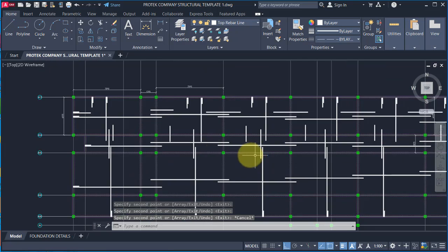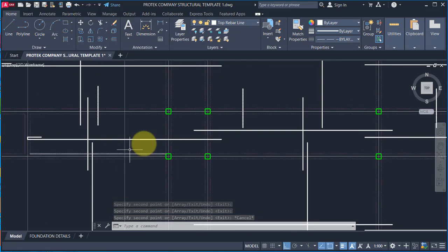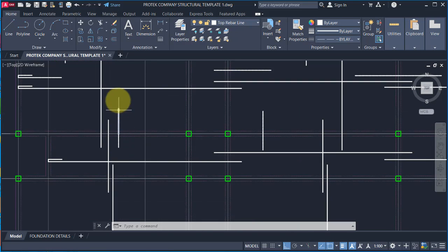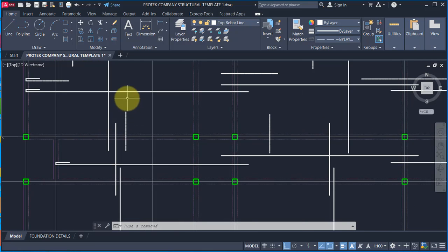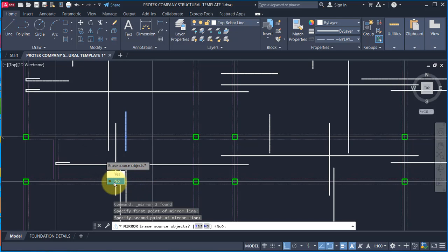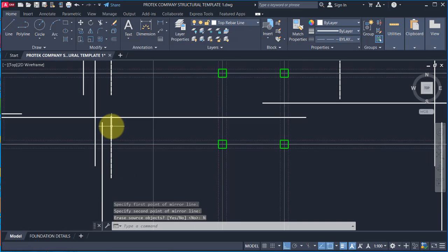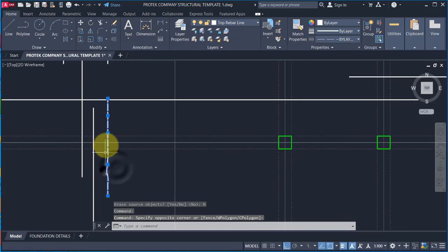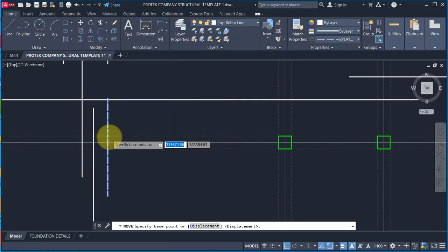Okay, all right, so we'll be having another top bar here too, so it's going to be more or less like opposite of this one. So you can just mirror this. You pick mirror, pick this point and turn it this way. If that is not the center, we will adjust that successfully. You just have to click and then select no options, then select these two lines and adjust this midpoint to be at the center of grid line. So it will move right there.